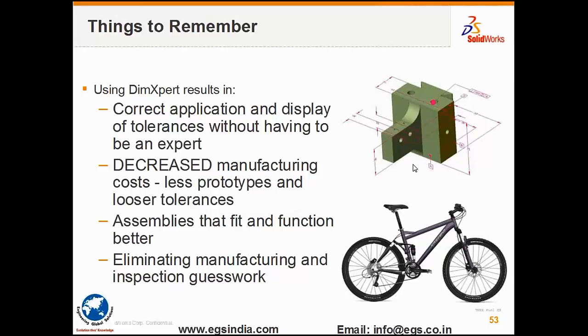Now, things to remember. Using DimXpert inside SolidWorks, correct and complete application of the tolerances without having to be an expert is achievable. That does not mean interpreting the drawing does not require an expert. It definitely requires an expert. But at least we are able to produce drawings without the manufacturing errors that typically come with less experienced engineers. Second one is the decreased manufacturing costs because less prototypes and looser tolerances are acceptable, and because we know exactly how those tolerances come in terms of the fit and the function, and eliminating the manufacturing and inspection guesswork.